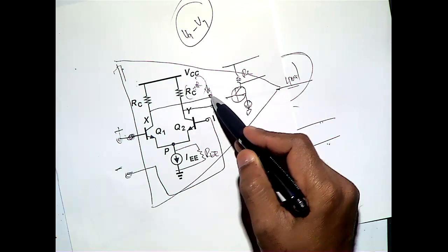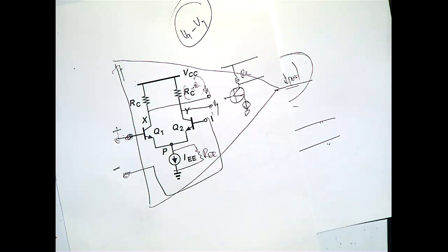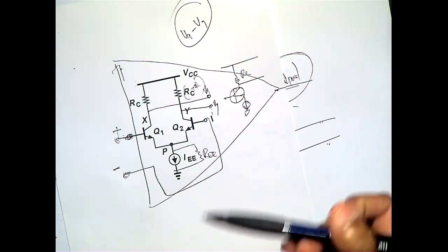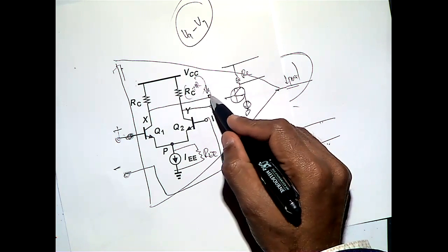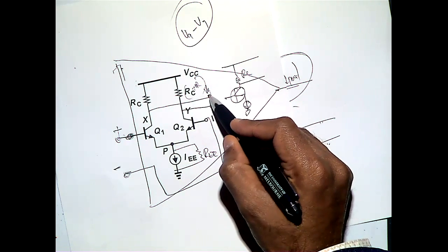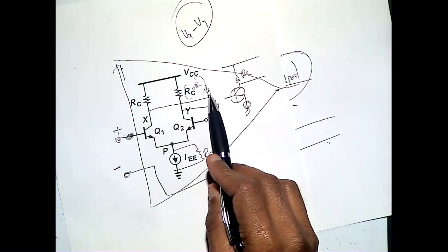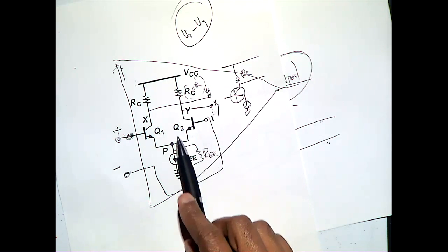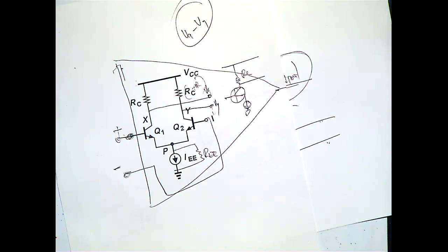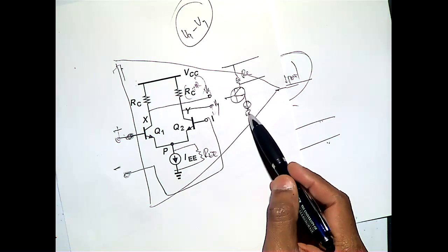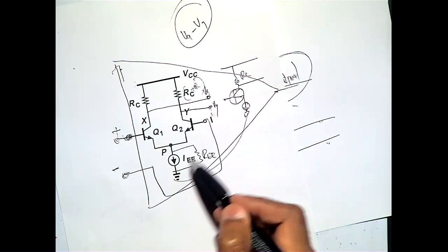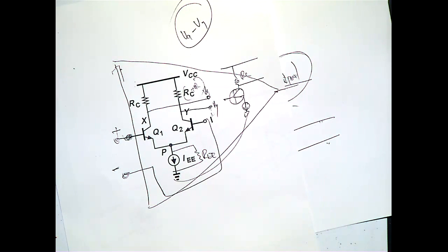And then if you take Vx, then what is the use of a differential amplifier? We can use two supplies, sir. Positive supply, negative supply. By that our VB2 won't be compromised. No. So then this is a VB. How will I connect this to here? Because you got Vx, I have to connect Vx minus Vy. That is a differential output. If you connect Vx alone, then you don't need the differential amplifier. You are not making use of the features of the differential amplifier. If you connect Vy alone, then you connect this ground with this ground, then you don't have the effect of the differential amplifier. You know what I meant?